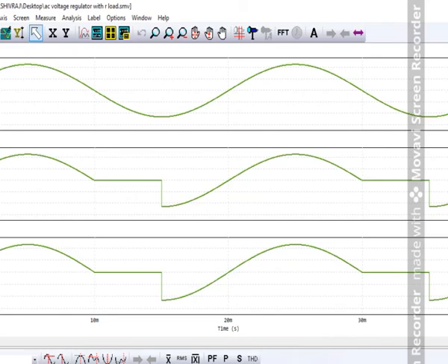during the positive half cycle, the complete cycle has been given. But during the negative half cycle, that is for thyristor 2, we have given a 90 degree firing angle. So that means up to 90 degree it will be 0 and it will be like this.